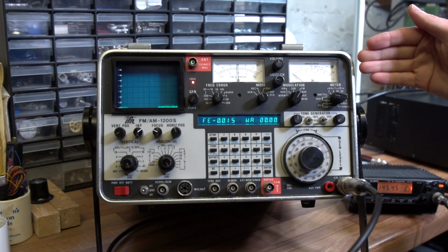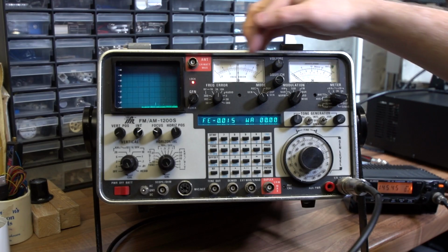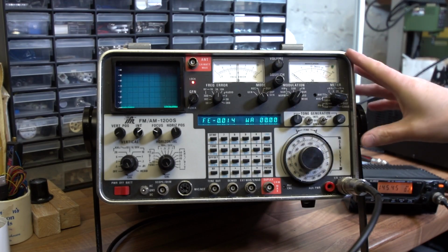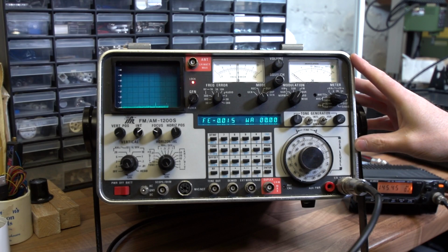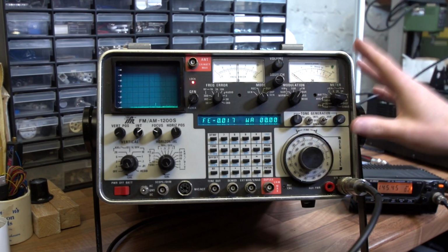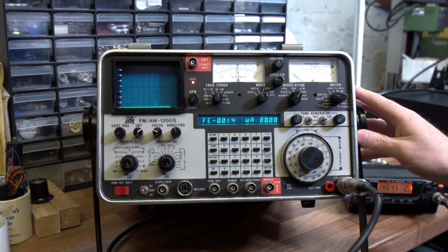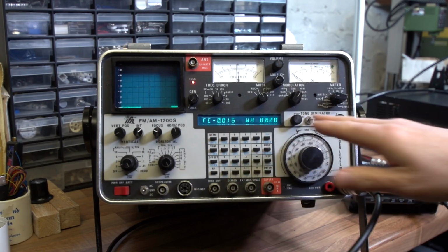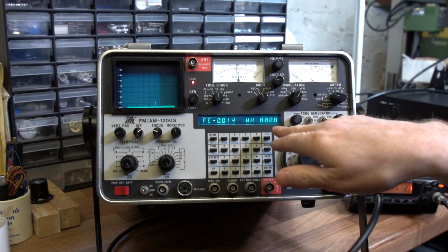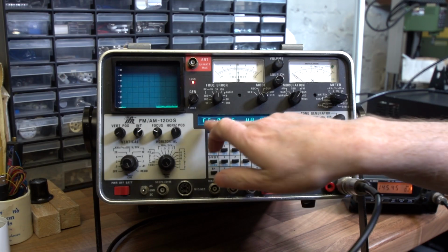It's also a power meter, and it shows deviation. It also shows frequency error. It has an error meter. One thing I should say about this particular model, even though it's very old now, is that it has a built-in crystal oven reference. So the internal reference is actually very good, and I've had it recently calibrated as well. It's pretty much spot on. So everything's reading correct. We have a digital display which gives us various readouts for frequency, power, frequency error, that kind of thing.